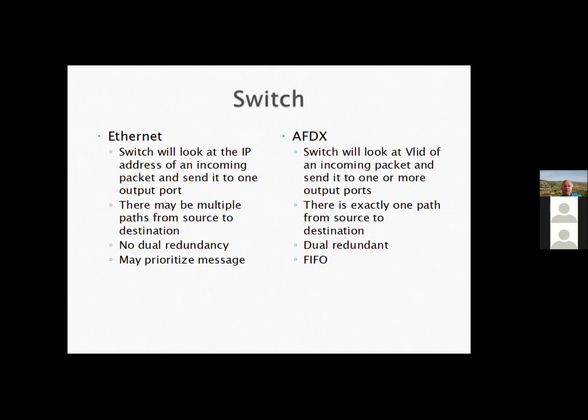In AFDX, it can happen, because we know when we build the plane exactly how many devices are going to go onto this AFDX switch, onto the whole network, and we know what the data requirements of all of them are. And if we build our plane intelligently, we'll make sure that all of the data requirements fit into the time that they have. So in other words, if you've got a device that needs to talk for 10 milliseconds out of every second, that means it needs 1% of the bandwidth. I can have up to, theoretically, 100 devices like that, and they'll all work harmoniously.